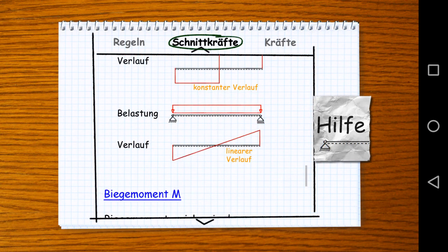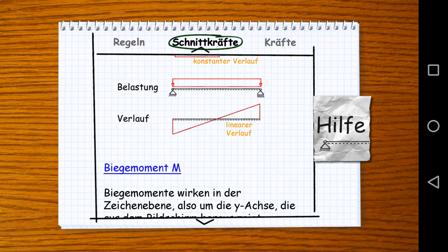distribution. And for the bending moment, we're going to try to picture how the beam, or how the system, is going to deform. The bending moment is going to be on the tensile side of the column, the beam or the rod. So when a beam is deflected, it has a specific curvature. We explained what a positive curvature is and what a negative curvature is, so that we can know on which side, and what the sign of the moment is going to be.